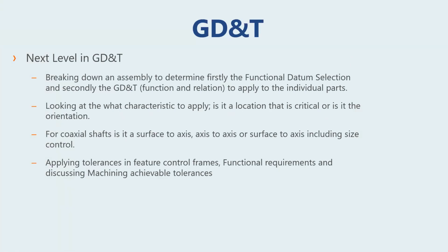So we start by looking at the physical assembly and how the part fits into it. By looking at that, you have a much better understanding of what that part actually does. And remember that when we produce a drawing of a part, we want to communicate to the individual making it, who might not have a clue where that part is going. So we have to dimension based on that.